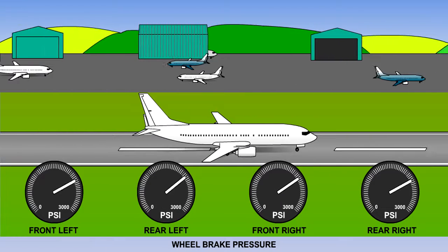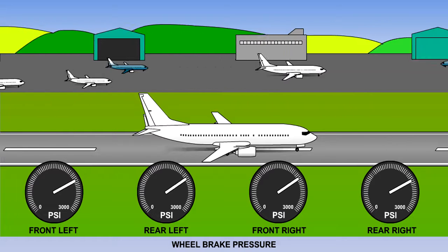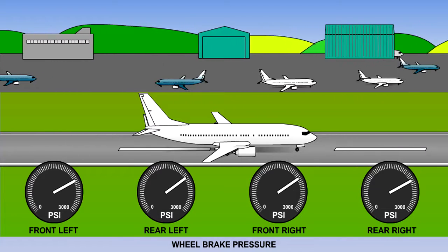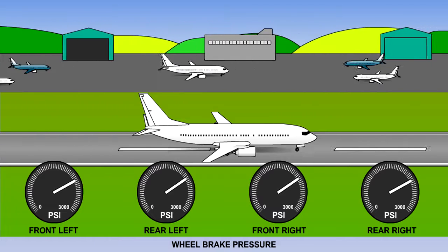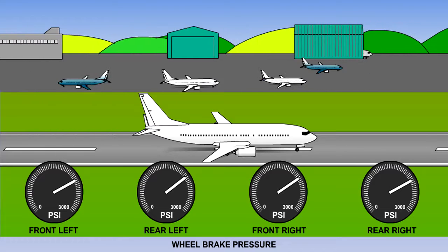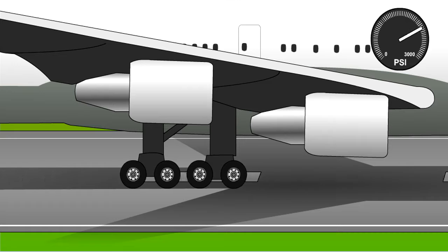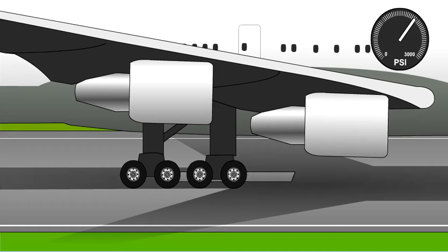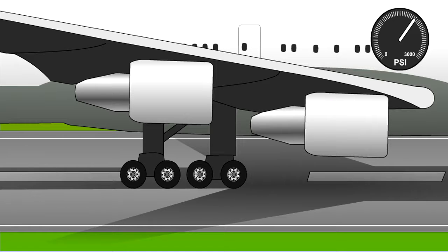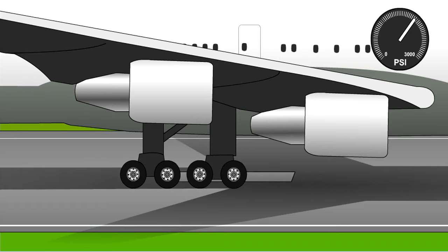For skid prevention, the anti-skid control unit will reduce the brake pressure to any wheel that it determines is approaching a skid by monitoring the deceleration rate of the individual wheels. It will then modulate the pressure to ensure optimum braking. Most electronic anti-skid units have an adaptive pressure bias modulation circuit. This ensures that with the pilot applying a constant pressure on the pedals, the brake pressure applied immediately after a wheel is released following a skid is lower than the pressure which caused the skid. This prevents an immediate return to the skid conditions that caused the anti-skid unit to release the pressure in the first place.